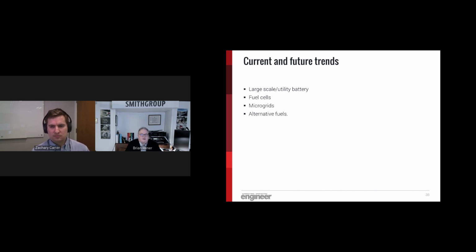And with regards to those two things, there's a lot of push these days about alternative fuels. You hear a lot of talk about hydrogen. Depending on where it's sourced from, there are different types of hydrogen, and it can be very clean or dirty hydrogen. But that's a great way that some of the generator manufacturers, particularly natural gas generators, are being made now to handle a blend of hydrogen and natural gas. There are also hydro-treated vegetable oils that are out now that are better than the old biodiesel that can run in diesel engines. So there's a lot of discussion and push for alternative ways to back up mission-critical facilities.